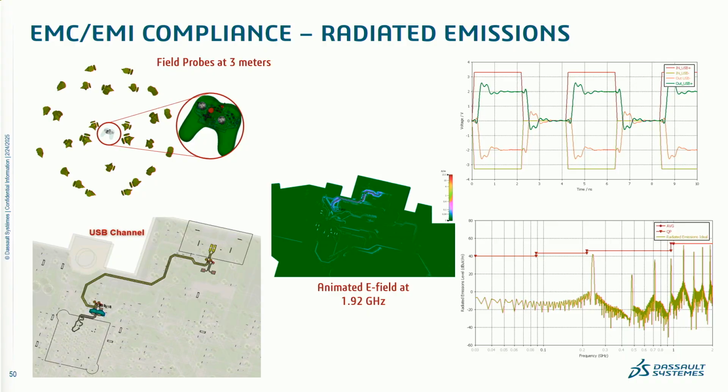But what we see in the bottom right, that is a radiated emissions plot, and you're seeing the FCC 15B, Class B, 3-meter, that's a mouthful, limit lines plotted up there. We are currently under all of those. We would pass that EMC test. But that's an ideal circuit.